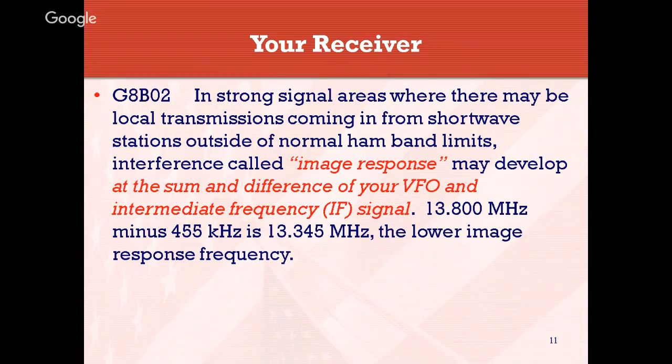And what it boiled down to, we even put in this 455 kilohertz frequency. And what we discovered was that cars passing in proximity of the repeater site tuned to a certain radio station were actually emanating a signal that was mixing with the receive side of the UHF.